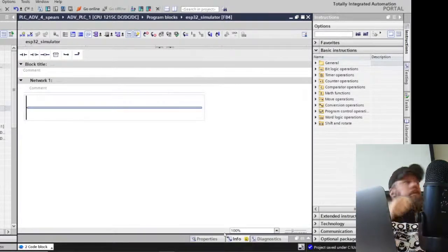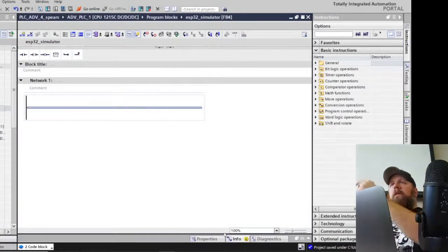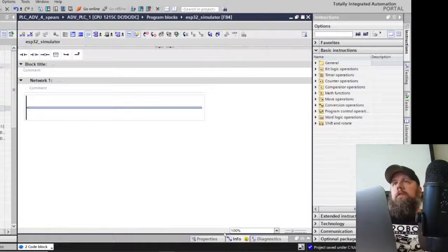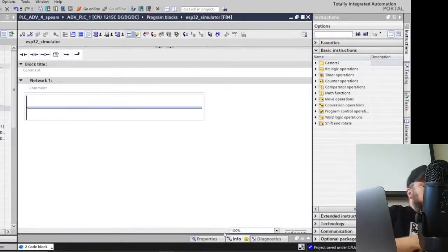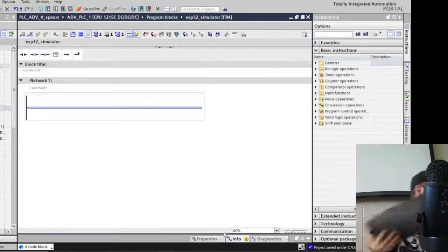So you'd be able to connect these modules up. Instead of wiring up to the PLC, you'll just plug in an Ethernet cable and plug in another Ethernet cable, and you've got this little board that you can put a bunch of stuff on. So the analog output 2 is going to go to that daughter board. It's just going to bypass that so that we can get 0 to 10 raw out. Let me draw that real quick so that we can reference it when we need to.